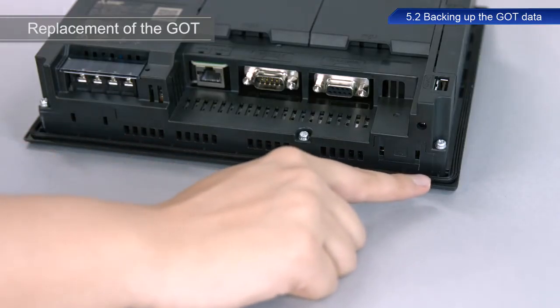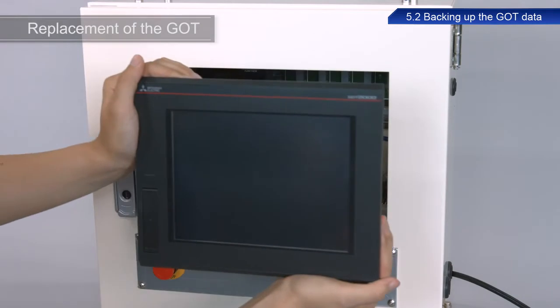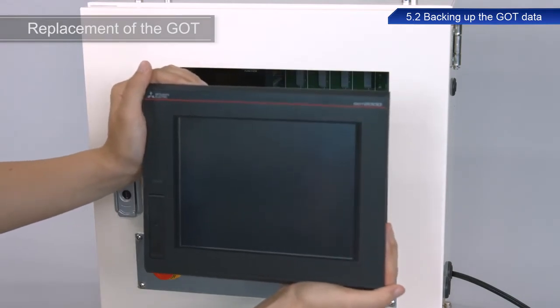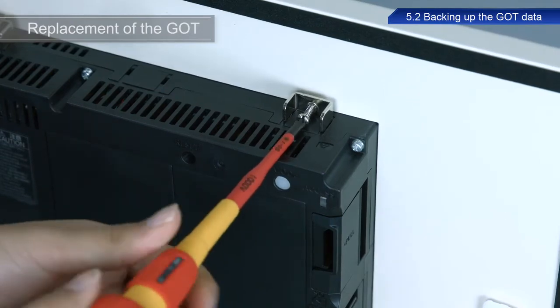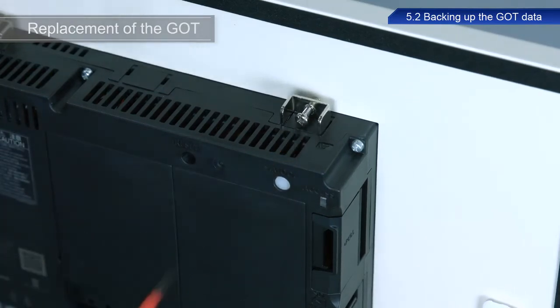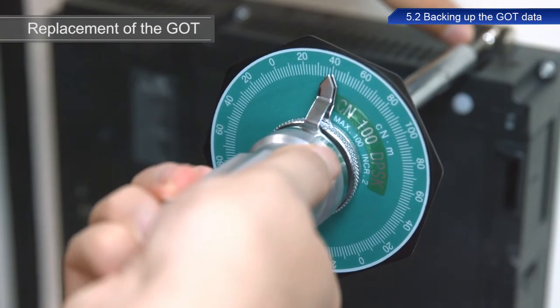Next, make sure the gasket is installed around the rear edge of the GOT. Insert the GOT device into the opening. Secure the brackets from the rear side. Use a torque driver to tighten the screws to a tightening torque within a range of 0.36 to 0.48 Newton meters.